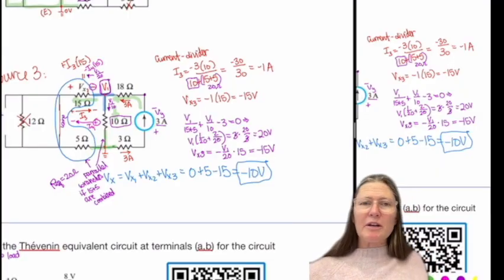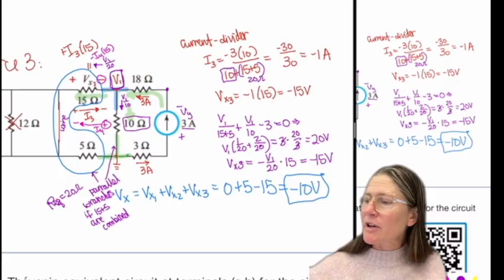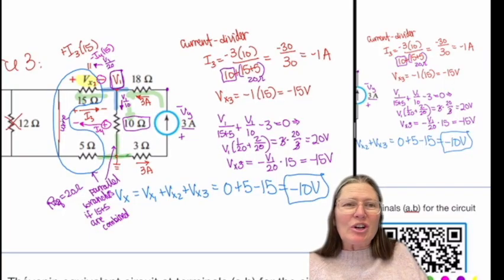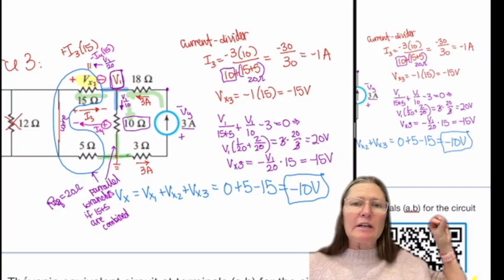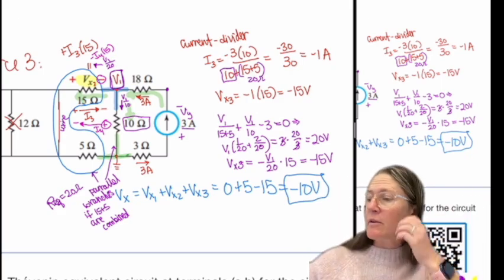So a quick comment about the previous one. I was looking at VX on the corner here. Solving for VX3, which is across here, would be V1 over 20, and it'd be minus because of the polarities.